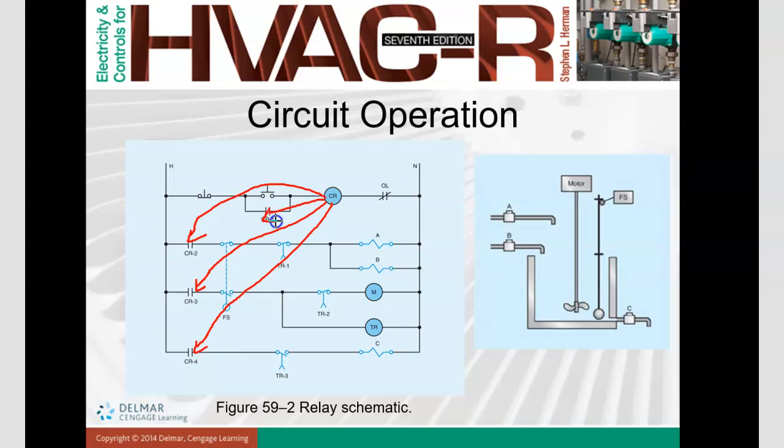Because this is a push start stop button, maybe it has a spring, so after one push it goes back up. Then what happens? The current is still going because we have a contactor relay over here. When this contactor relay still has current, this is still energized. The current will keep moving until we manually push this stop button.